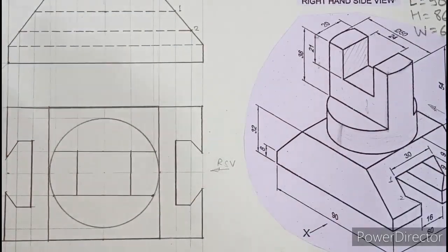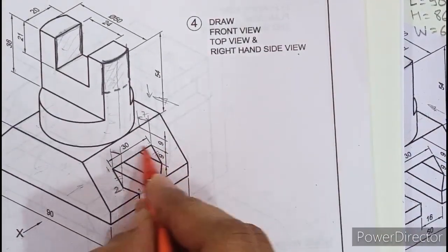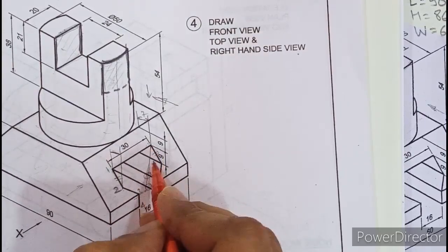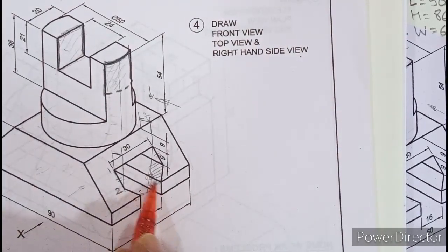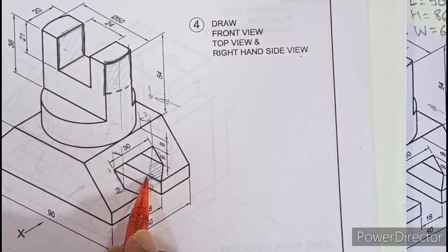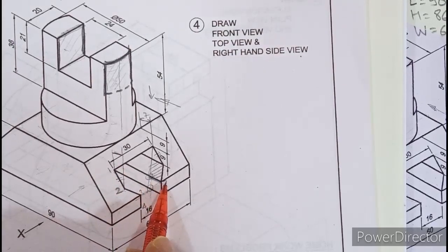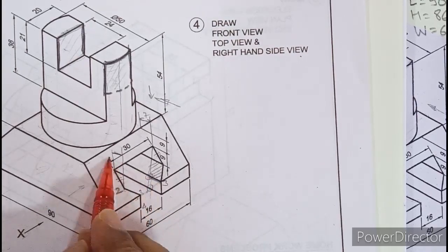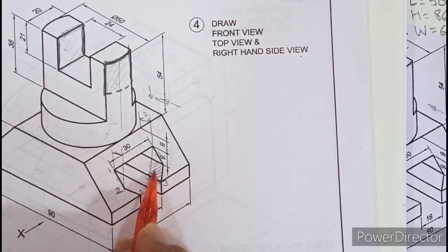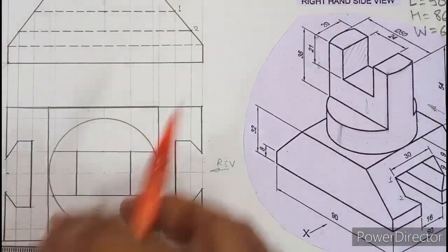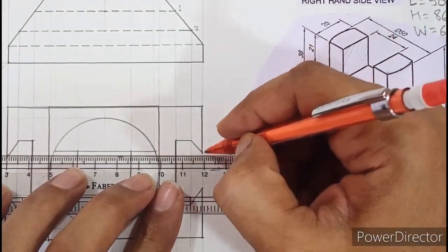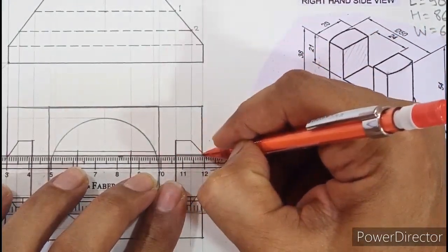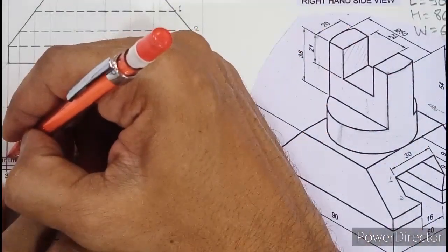Now, as we discussed before, in the top view, if you look at this slot thoroughly and if you project this point down, you can see some portion of this slot, isn't it? So this edge will be seen up to some extent, then you cannot see it. So from point number 3, this is a point number 3, some portion of this edge will be seen, remaining will be hidden, because the surfaces of its tapered nature will be seen from the top view. So from here, if you align these 2 points, you can see up to some extent, this edge will be seen. From here also you can see that edge.